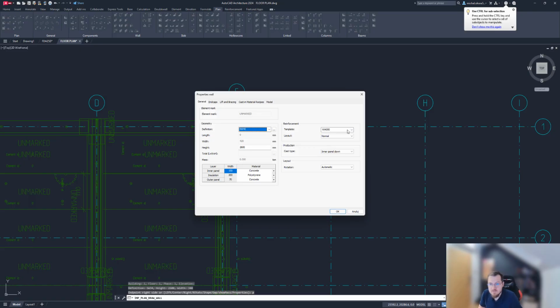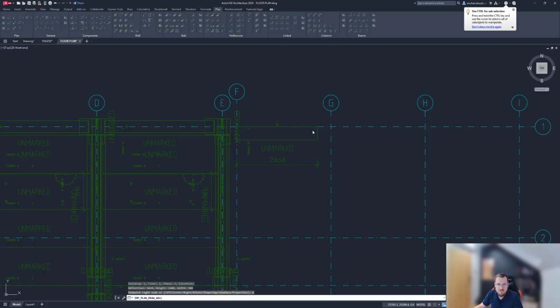Why the reinforcement templates? So you don't have to think about manually adding all the reinforcement into your elements at the drawing stage. The reinforcement template will be applied at the moment of you drafting the element, once it's complete, and you can open the drawing once it's of course prepared in Impact, and you can go ahead and actually edit that reinforcement to make it fit your needs, of course. So with that, let me go ahead and actually start placing that.